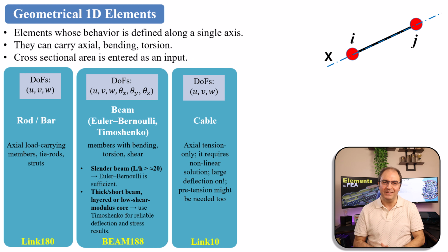Next are cable elements. Cables are designed for axial tension only. They cannot resist compression or bending. Because of this behavior, cable elements almost always require a non-linear analysis, especially when large deflections are expected.